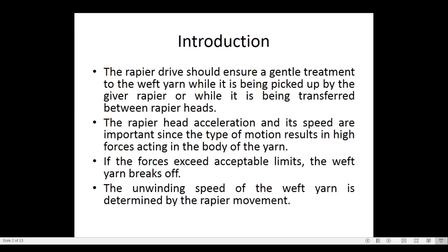So always the load on the weft, the tension or forces on the weft, should be less than the 10 kilo breaking force. If the forces exceed acceptable limits, the weft yarn breaks. So when the tension in the yarn goes beyond this limit, the weft yarn breaks. To keep the tension within acceptable limits depends upon the drives. So if more weft breakage problems are coming in the shuttleless loom, even though your shuttleless loom is costlier and you are unable to control the weft breakages, it means your drive is faulty or some setting is wrong in the drive.